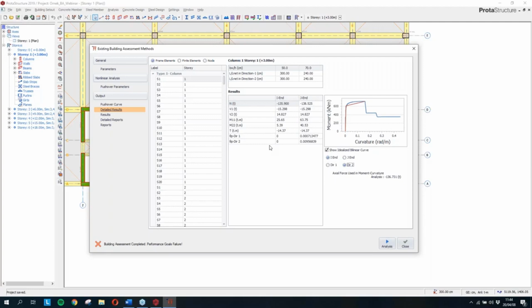For shear walls, we are also using 6 integration points, and we do not concentrate on one region. We simply give a nonlinear definition to the whole member, at the integration points.